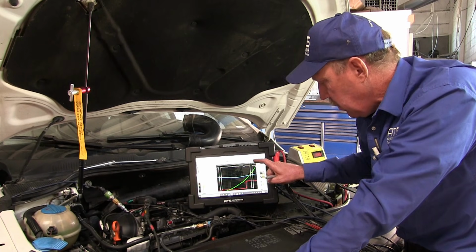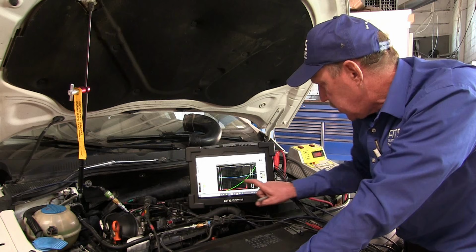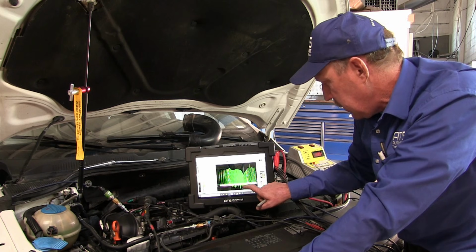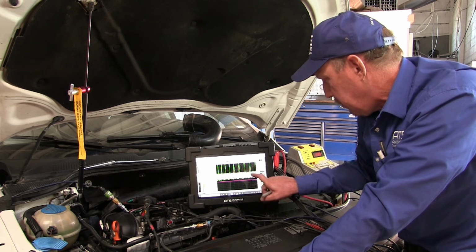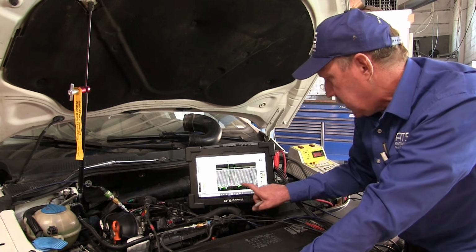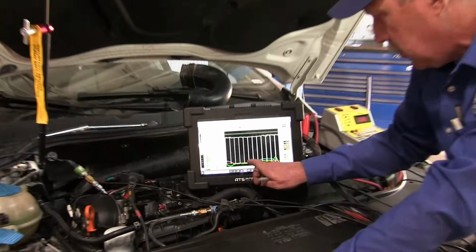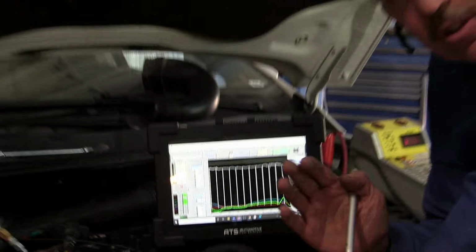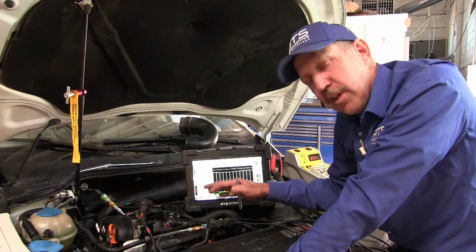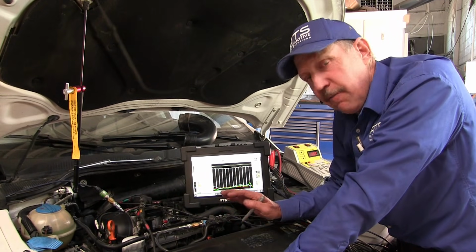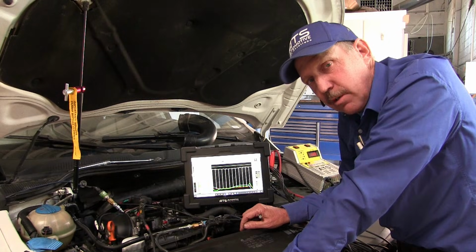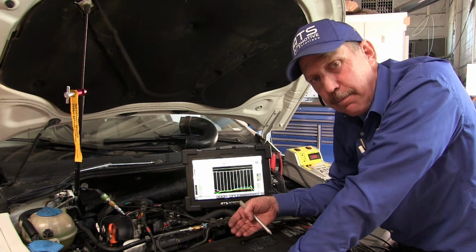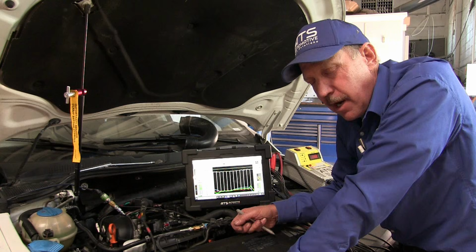These are its normal off position. So you'll see these types of waveforms when you get these cars, and they'll have this type of pulsing waveform. But to actually get this to change, the duty cycle needs to come on longer. So this is in an off position, which is very normal. Once I set a code for the cam crank correlation, manufacturers don't go ahead and control the system anymore. They stop controlling it because they're worried that if the cams were off and they applied them, they could bend a valve. It's one of the possibilities.